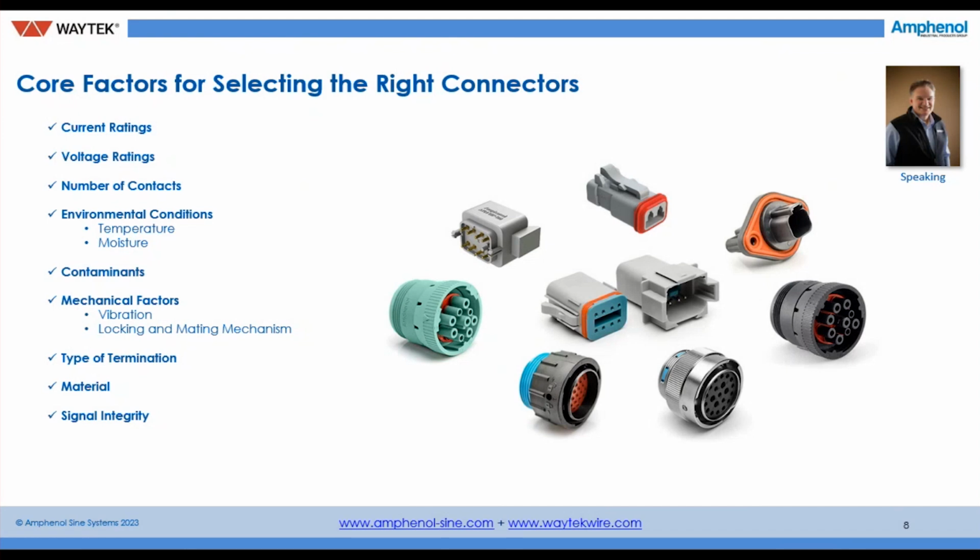Types of termination could be solder contacts, could be machine contacts. Material, plastic or metal. If it's a salt spray environment, certainly customers are going to want to lean towards plastic. If it's a drone application, metal may not be preferred because of the weight contributions. But if it's a rugged environment where maybe limbs, trees, thinking of forestry, may come in contact with those connectors, a robust metal connector could be all that's needed.